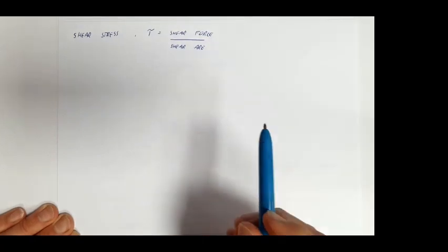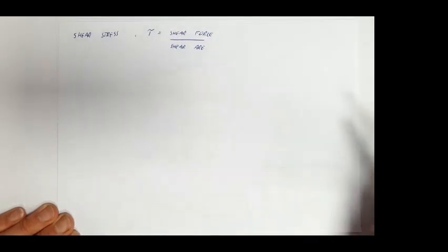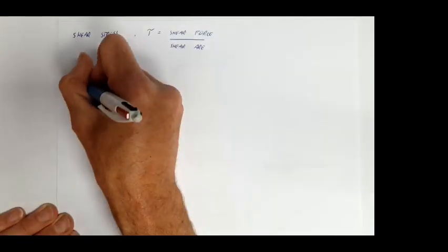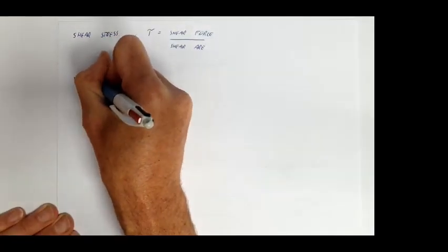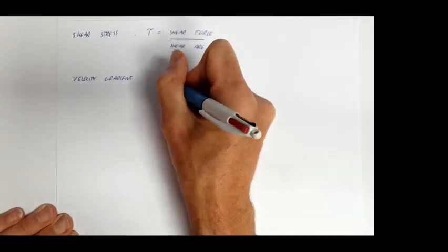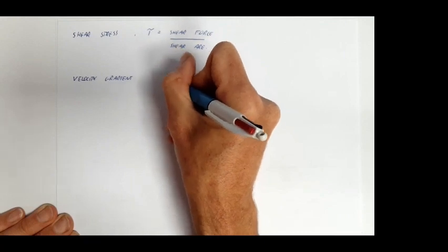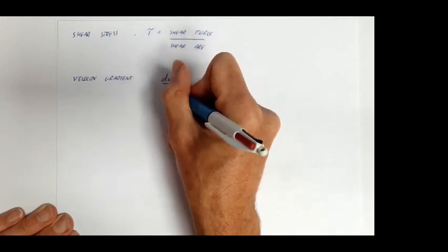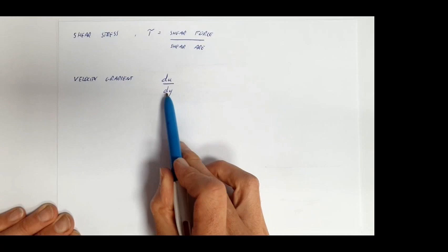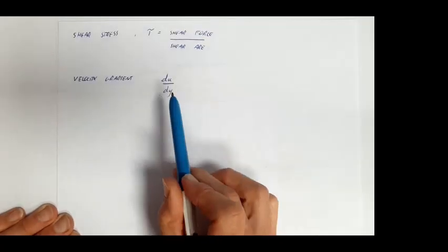And dependent on how viscous a fluid is, that will determine the velocity gradient, like I was talking about earlier, how quickly we go from that zero velocity to that free stream velocity. So our velocity gradient is clearly influenced by that viscosity. So our velocity gradient, that's du by dy. So the velocity, change in velocity as y changes, if y is the distance away from the wall.